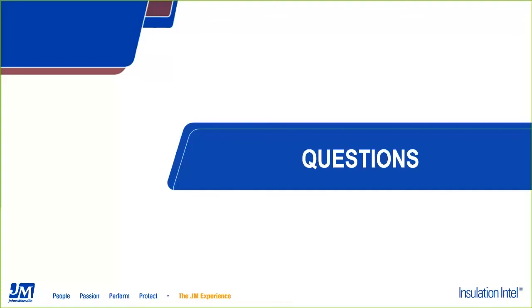All right. The next question is, as per NFPA 285 section 5.7.3.2, no material shall be used to fill air gap cavities, if any, or further cap the header, jambs, and sill areas. Does this mean no cavity barriers can be installed within the cavity around the window opening? Yeah, I'll take this one, guys. This is directly out of the NFPA 285 handbook. And the answer is, so there's kind of two options there. The answer is essentially no.